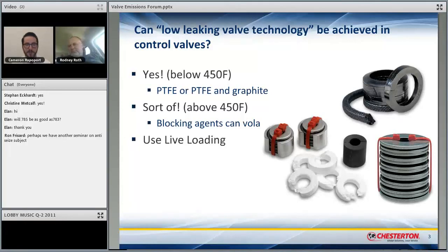So you mentioned why methane was chosen. I'll just reiterate that briefly, because people do ask about methane. ISO's original test media was helium, and the European standard, the German standard TA Luft, also uses helium, and API uses methane. ISO has recently adopted the addition of methane because it is more like what you see in the field. So that's why.